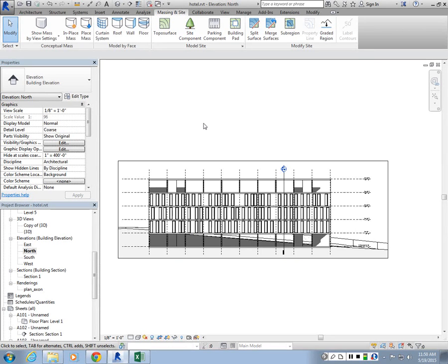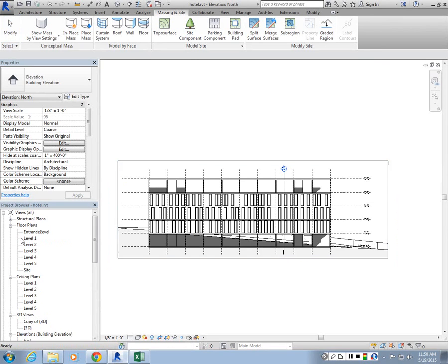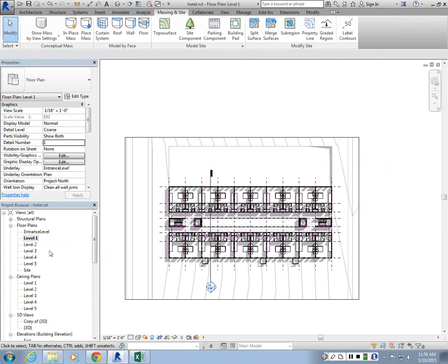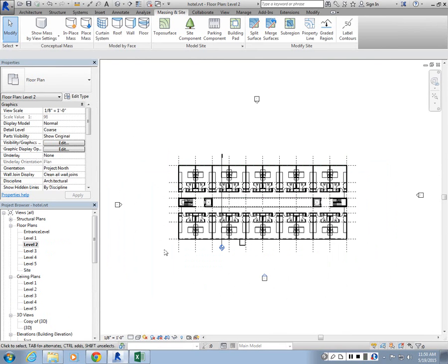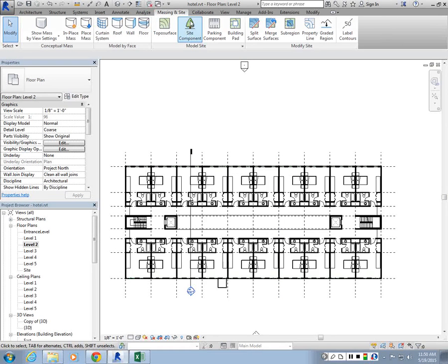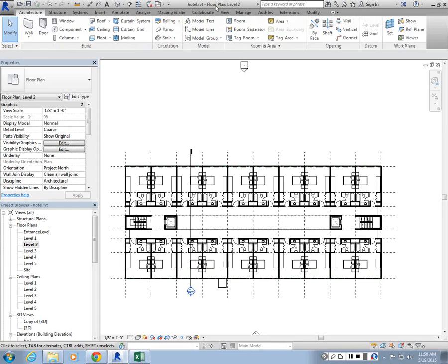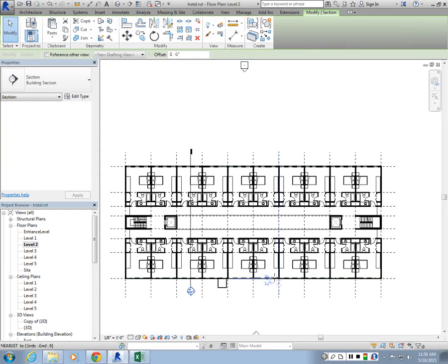The elevation cut you can control on the plan view, right? If you go to the viewports, this is the location of the elevation. So there will be a plane here that is cutting all the modeling and looking to the building. And if you want to add, let's make another section. Go to view, section. Let's say we want to cut here.